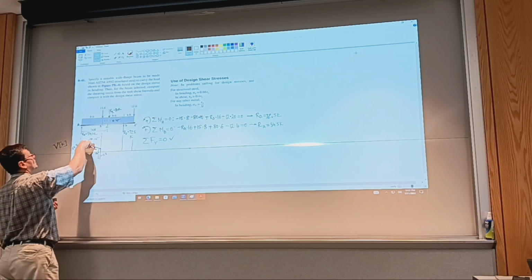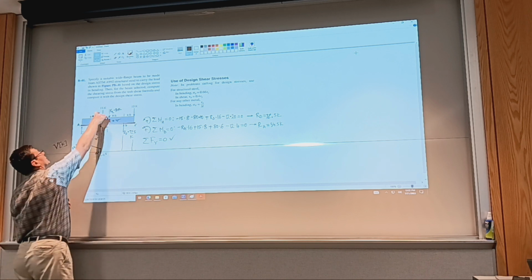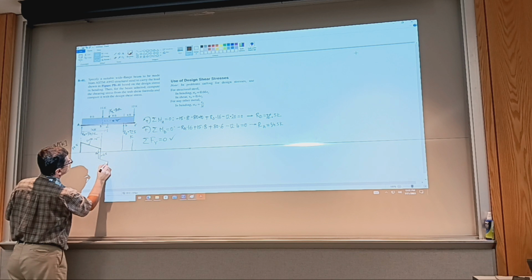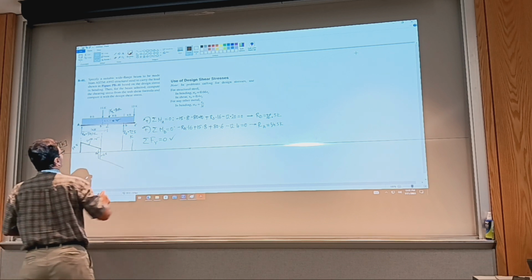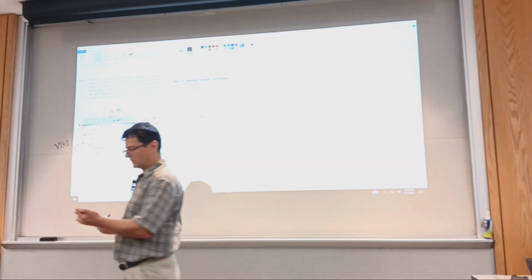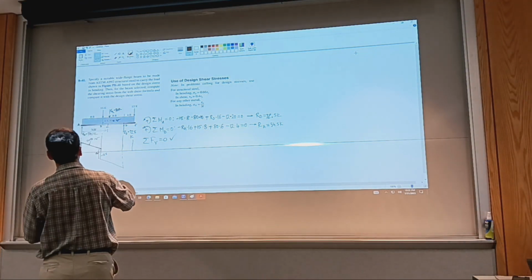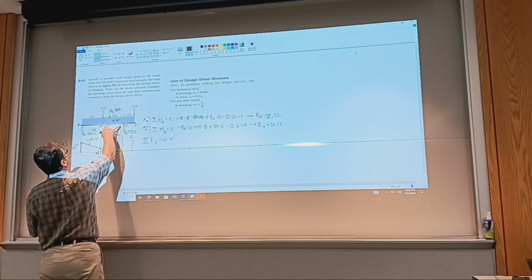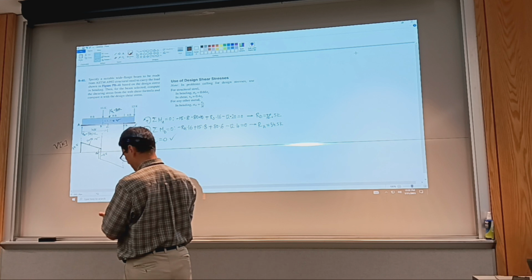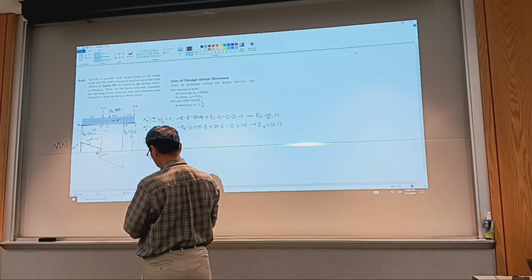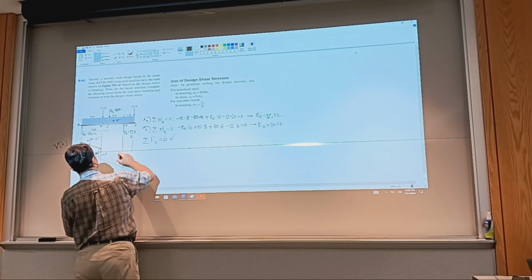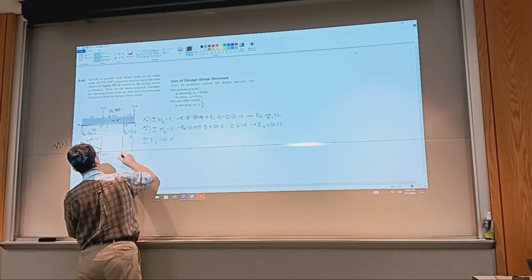It went to negative 12.5. And it continues on the same slope. So it was a jump because of this. Slope remains the same, so I'm extending this. So let's see where we're at D. We're having negative 12.5, to which I'm adding another 8 times 4. So negative 8 times 4, it goes to negative 44.5.